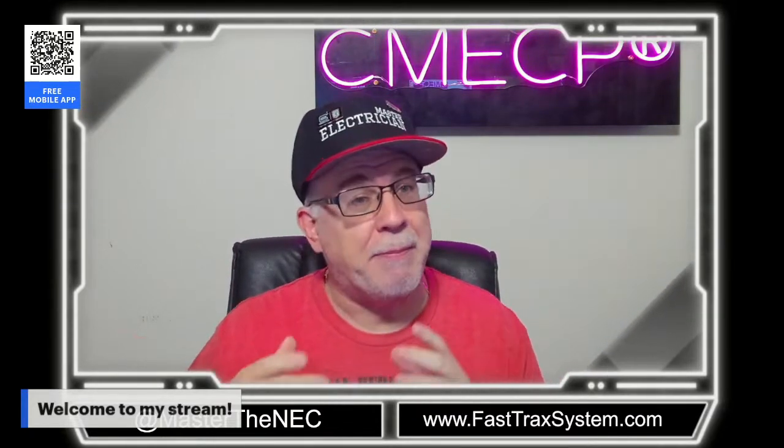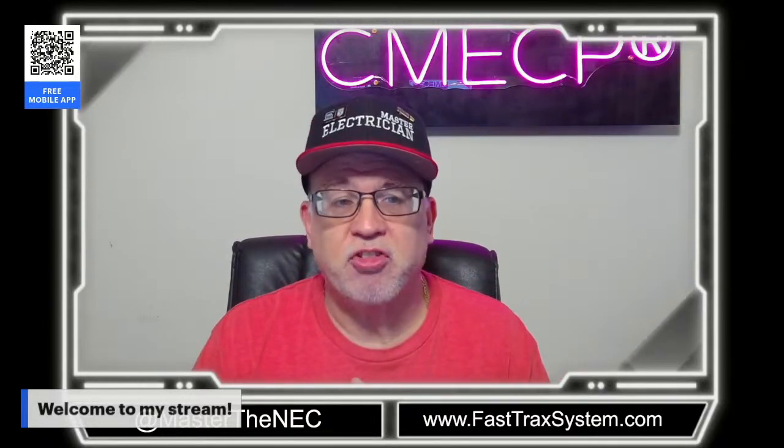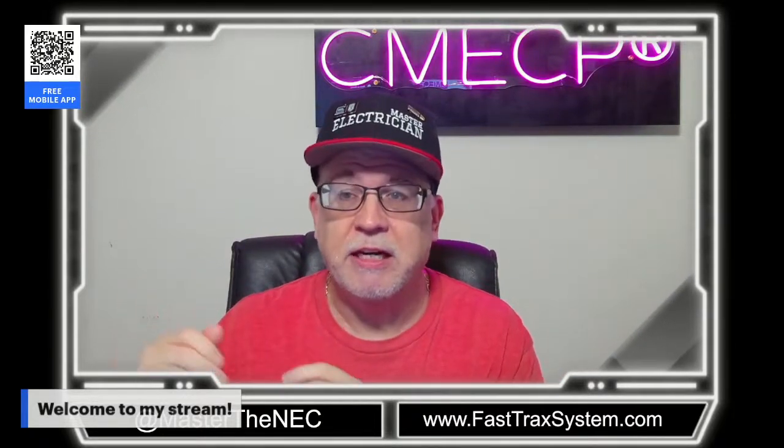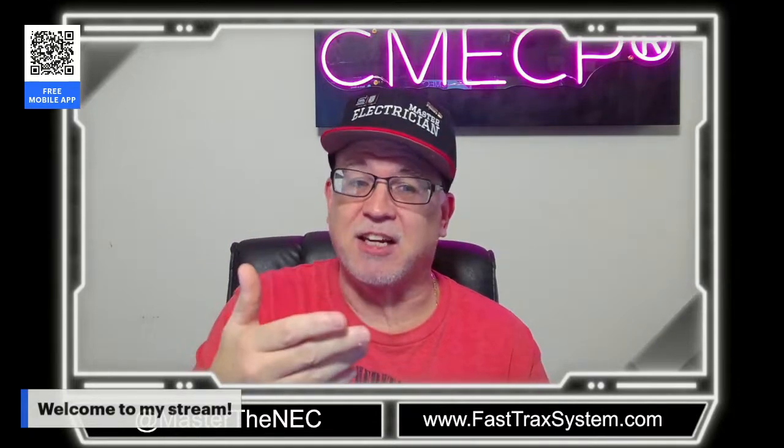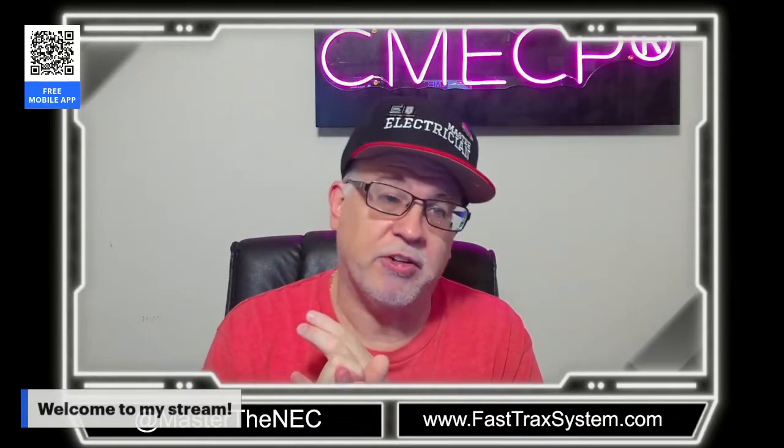Okay? If I do use a portable generator to supply power to a dwelling, then I want to make sure that if it is a bonded generator, I have a transfer switch that switches the neutral. If I'm using a floating neutral generator, then it's okay for me to have a transfer switch that is solidly connected, not switching the neutral. But again, you only want to use the floating ones on a premise application, because we just saw what happens if you use it as a standalone. The GFCIs won't function and the overcurrent device likely won't function, so that becomes a safety hazard as well.